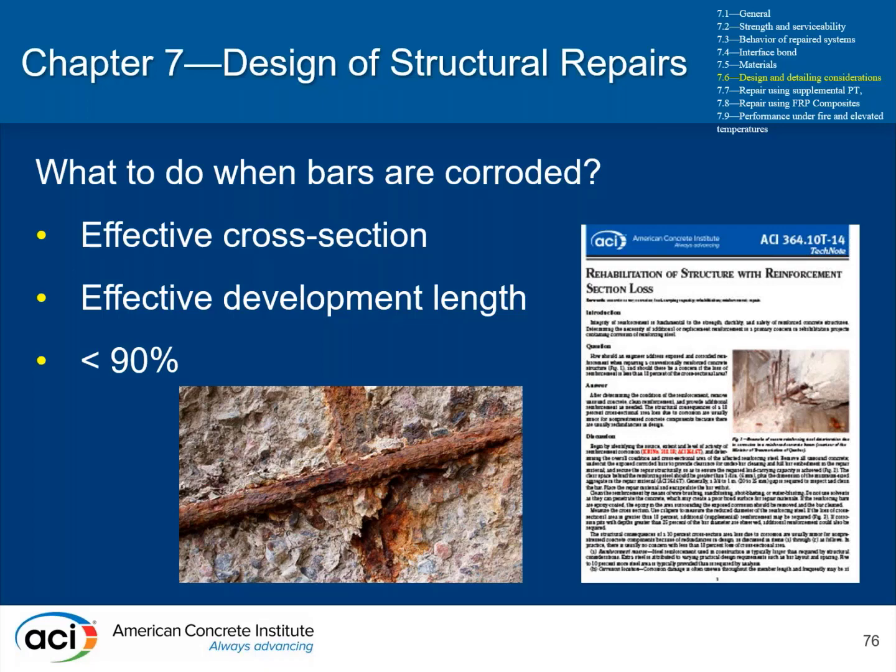As can be expected, there's oftentimes some subjectivity, frankly, that comes into play when you're evaluating corroded structures, and the experience and knowledge of the licensed design professional needs to come into play, helping to understand what happens if there's spalling, how does that impact compatibility, and how does it impact the composite nature, et cetera.